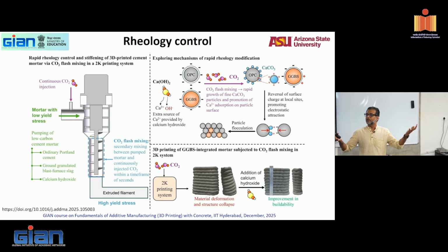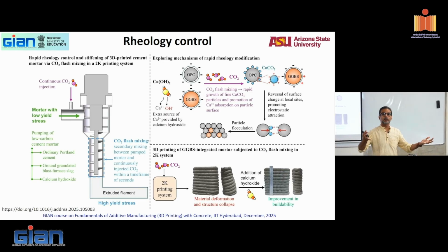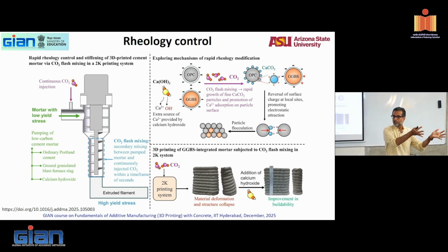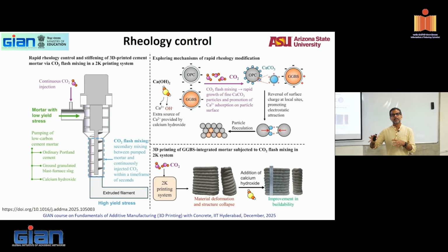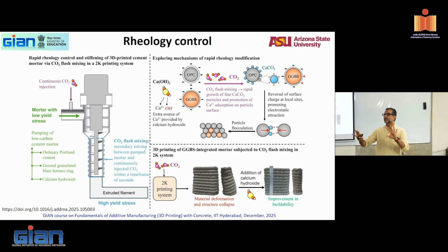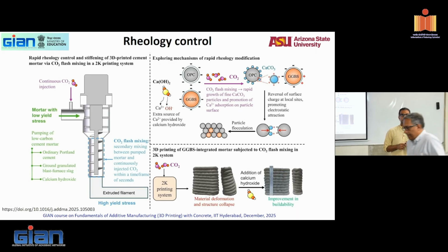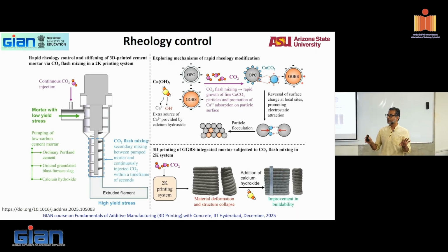And that's why I gave you the example of a ready mix concrete guy who will have an M30 mix made. So similarly, you know that this is printable, but then depending on the situation, depending on your material, your printer changes, depending on environment, you make whatever minor changes required to ensure that your structure is extrudable and printable. Is that idea clear to everybody?